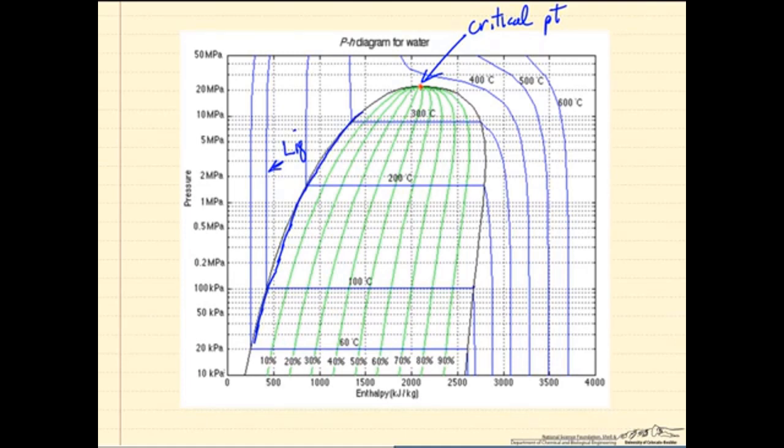And we go to saturated vapor. Of course, a big change in enthalpy due to the heat of vaporization. And now for the gas at 100 degrees C, the enthalpy is pretty much independent of pressure, and this is behaving very much like an ideal gas because we're at relatively low pressures, 100 kilopascals and lower. If we go to 200 C, it's a very similar behavior. However, at 300 C, things are different.